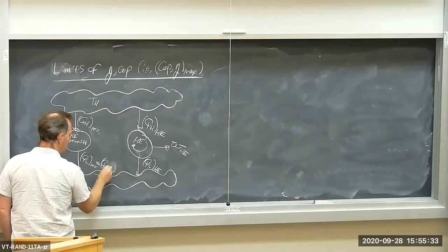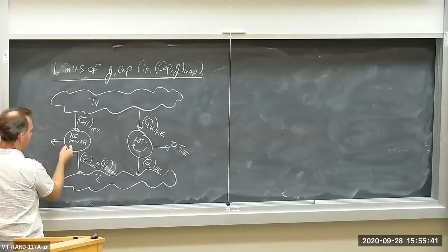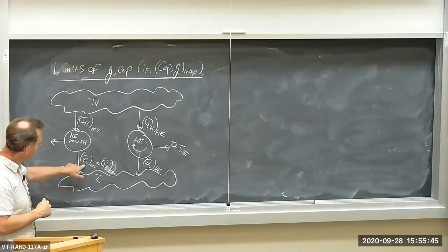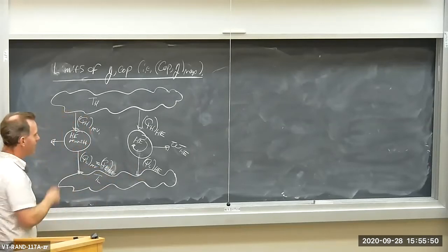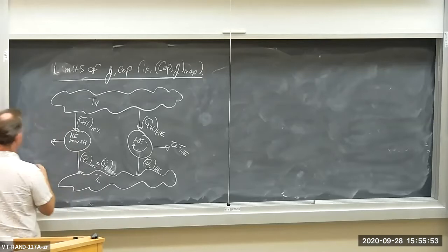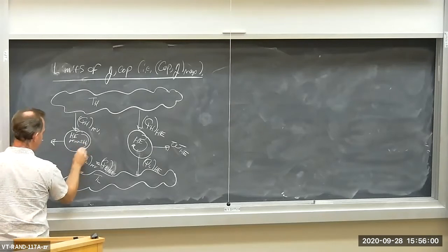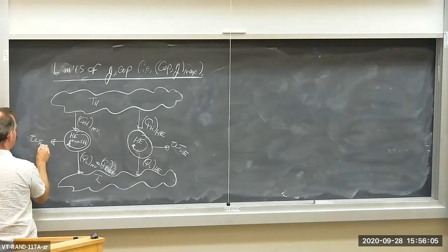Let me get my notation right. QL heat engine. So I've changed the size of my reversible heat engine, made it bigger or smaller, until the heat rejected by the reversible heat engine is numerically equivalent to being rejected by the regular heat engine. Now, of course, this thing is producing a certain amount of work. It's a cyclic device. So this is producing a certain amount of work, and this is our reversible heat engine, okay?